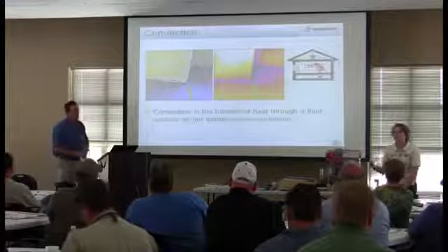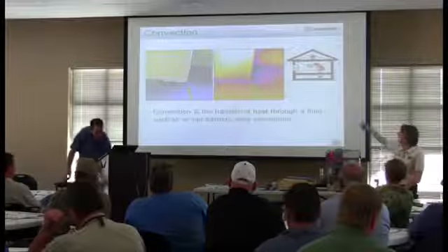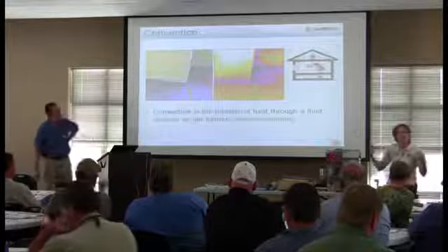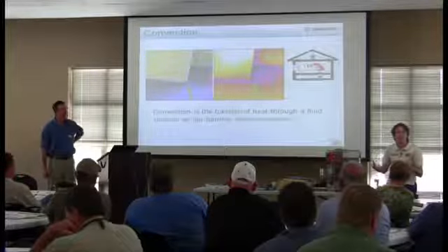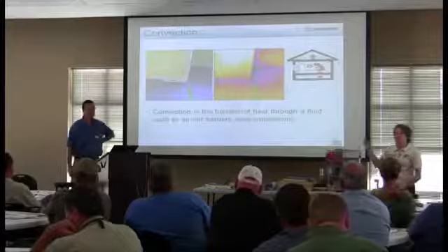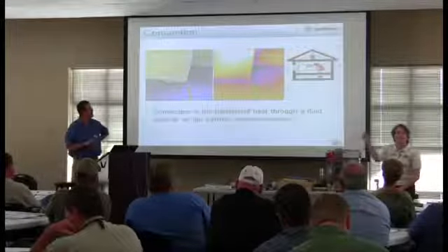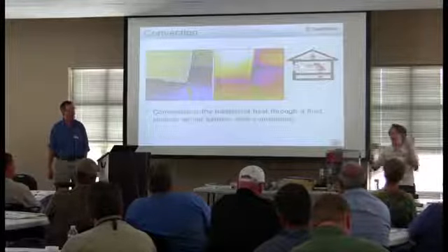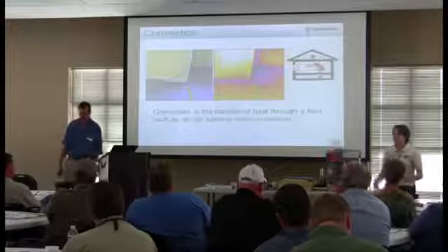The homeowner was complaining of some comfort issues. And what's going on, as we can see in the infrared picture on the right, when we turned on the camera and let some air pass through the house, cold air is coming up through the bottom of the house and going into the house from the bottom plate. So what does that indicate? What didn't happen on the bottom plate there? It didn't get sealed. There are some ways that you can seal it. Mike's got some there. Caulking works well. You need to stop that, because cold air comes into the house and starts to circulate, and that really causes comfort issues due to convection, that heat transfer through convection.